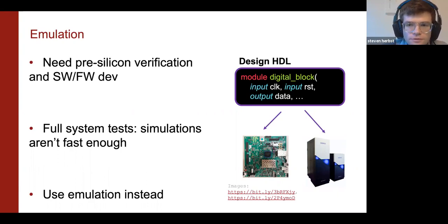So what's often done instead is we take digital parts of the design and map them to an emulation platform, which could be a commercial FPGA board like the one that I've shown here, or it could be a commercial emulation platform like ZeBu from Synopsys or Palladium from Cadence.